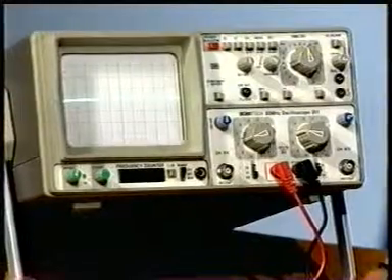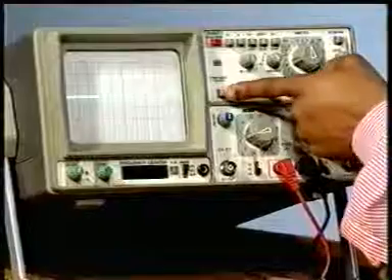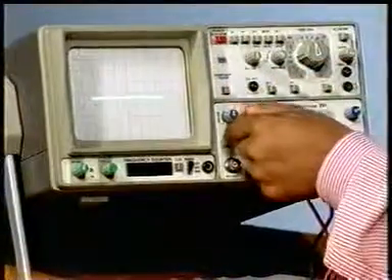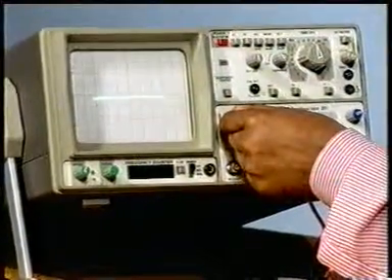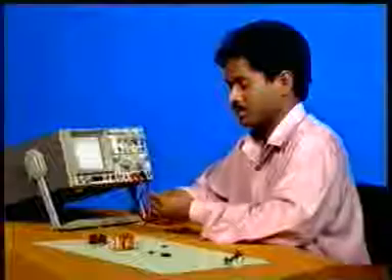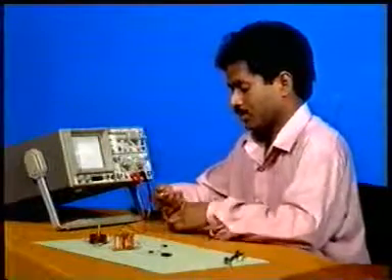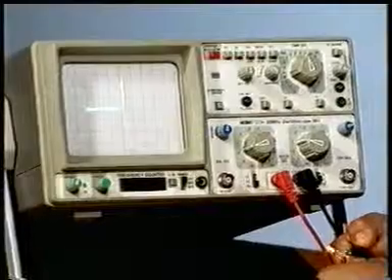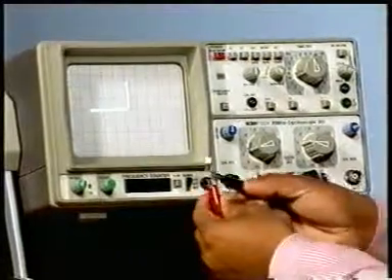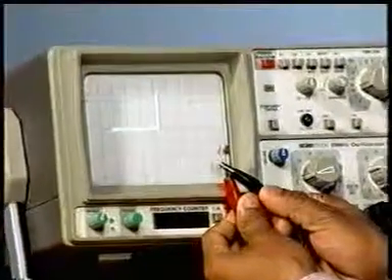Now I request Mr. Singh to demonstrate it on the CRO. So first of all he is to put it in CT mode, he has pressed the button and now he is to balance the beam. Okay. Now the transistor, he is going to check transistor, and for transistor he will check it between base and collector. Okay. Between base and collector, is it? Yes. So he is getting this pattern. So this shows that the transistor is healthy.